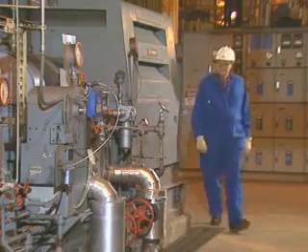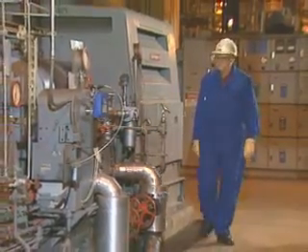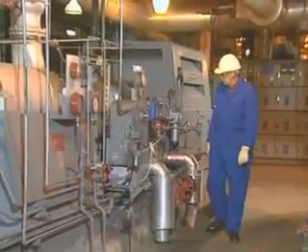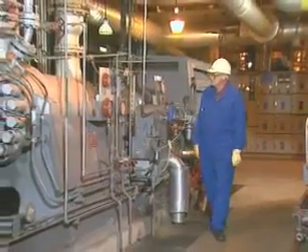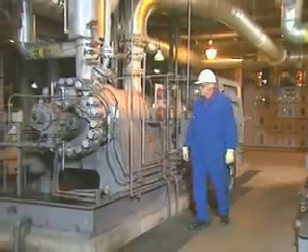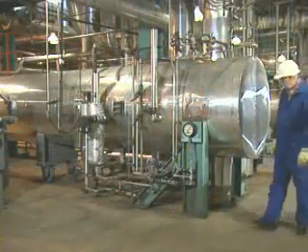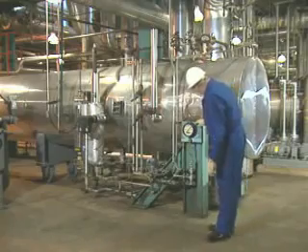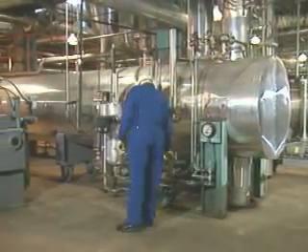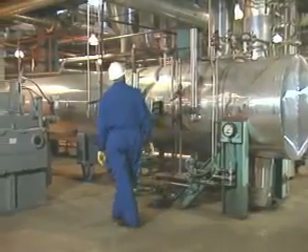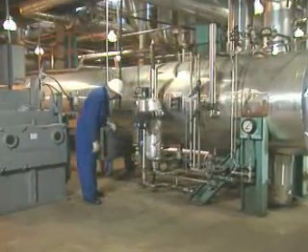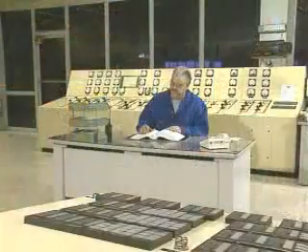If you're responsible for keeping a condensate and feed water system running smoothly, you must be thoroughly familiar with normal operating conditions for the system so you can distinguish between usual and unusual conditions. Making regular checks of levels, temperatures, pressures, flows, and valve positions throughout the system as it operates helps you detect problems early so that major trouble and costly downtime can be prevented.